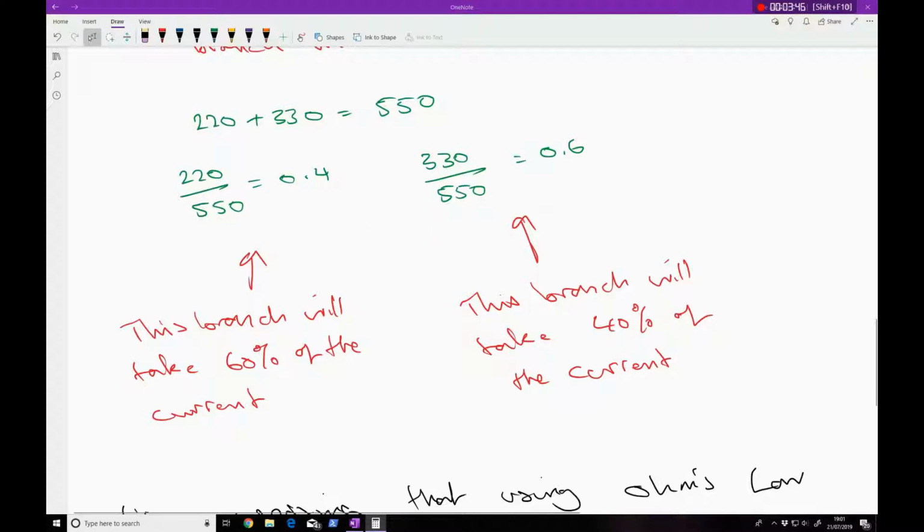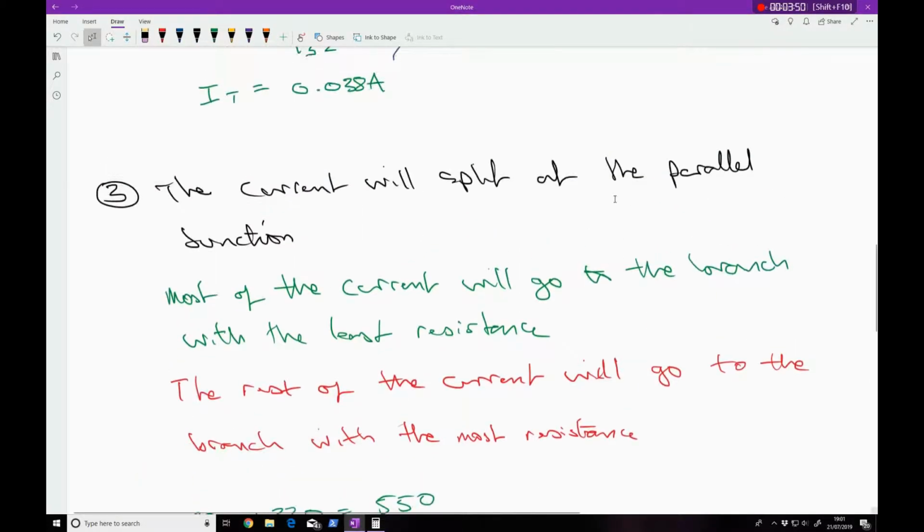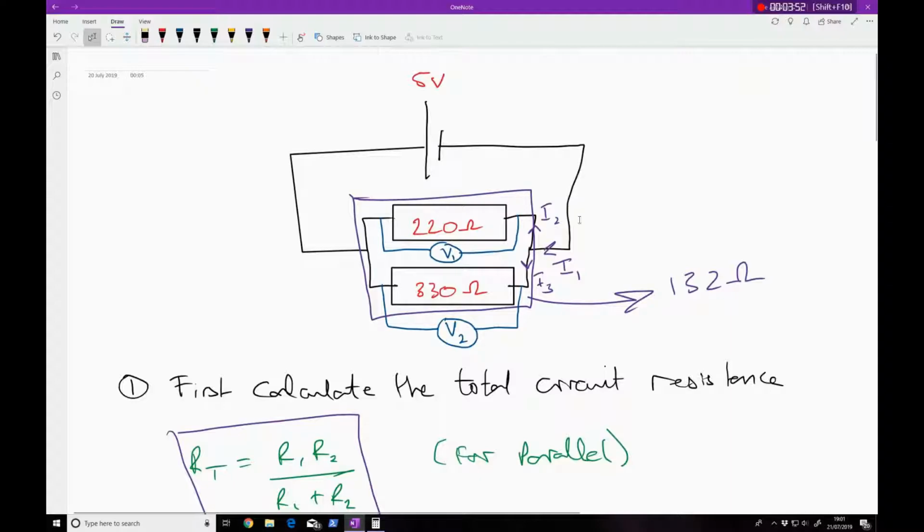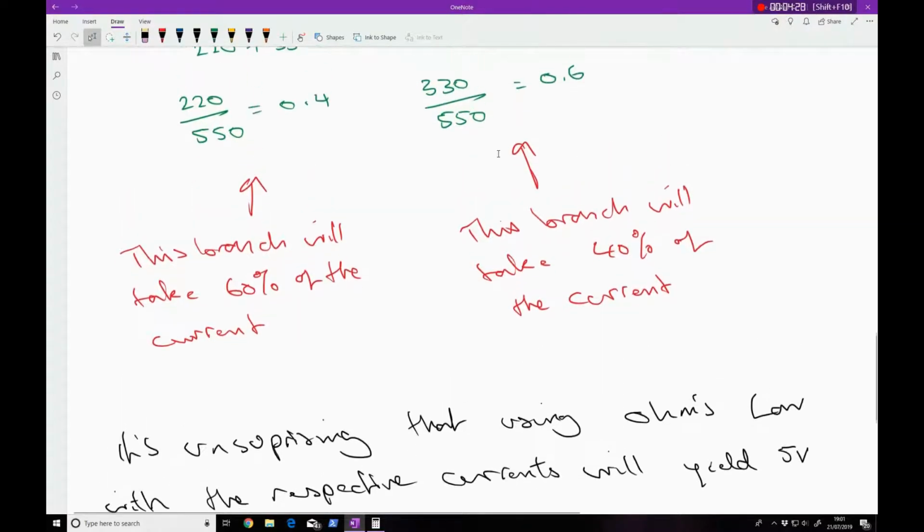the same voltage across each resistor. So 5 volts comes in there. Now this current I2 still has 5 volts in it. And this current I3 still has 5 volts in it, because nothing has been used up even until they get to the junction. So even if more current goes in there and less current goes in there, each electron within that current still has the same energy per unit charge. So 5 volts has not changed until it gets lost on the resistors. So these two voltmeters would read about 5 volts each, and we can calculate it as well.